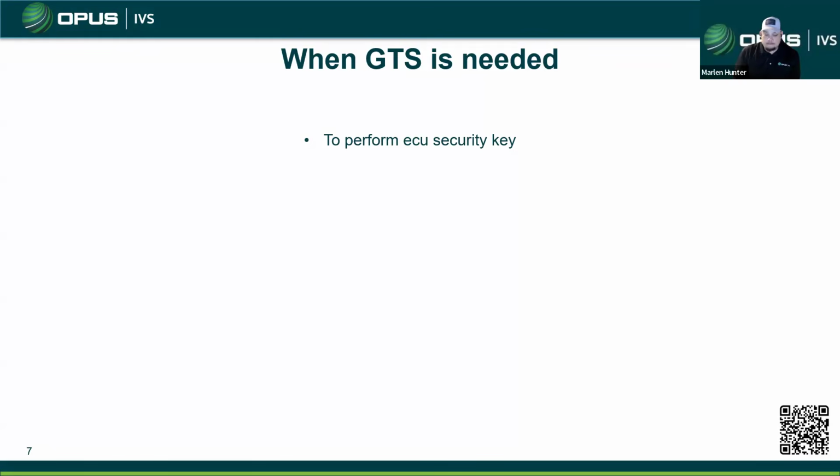So for years, Toyota has let us use modules on pretty much anything except the actual mobilizer system. What we're starting to see now, this kind of came around 2018, 2019, they brought this in for parts like the camera and some of the blind spots. That way you didn't reuse a part that was potentially damaged from another vehicle, just due to the nature of it being a sensitive part. But now we're starting to see them once you get into 23, 24, even 25s. I've had to do an SRS module, steering angle sensor, all your blind spots, both sides, your camera, your radar, and we're starting to see it on some ECMs.